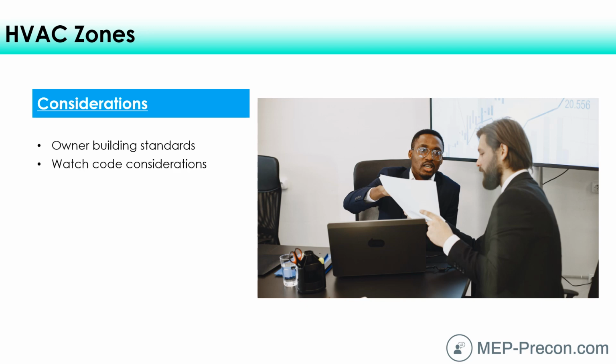An occupancy sensor would sense if there's one person in that conference room, but a CO2 sensor wouldn't change much if there was 0 or 1 person in there. But if there were 15 people in that conference room, it would react differently. It would bring in more fresh air that way. So those are considerations from an energy standpoint.